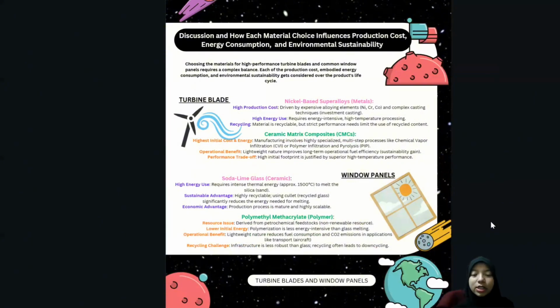Good evening, Doctor. I will now present the conclusion and discussion for this presentation. To conclude, overall, the selection of material for turbine blades and window panels really comes down to balancing bonding type, performance, cost, and sustainability. Starting with turbine blades, nickel-based superalloys are still widely used because their strong metallic bond provides excellent strength and creep resistance at very high temperature.